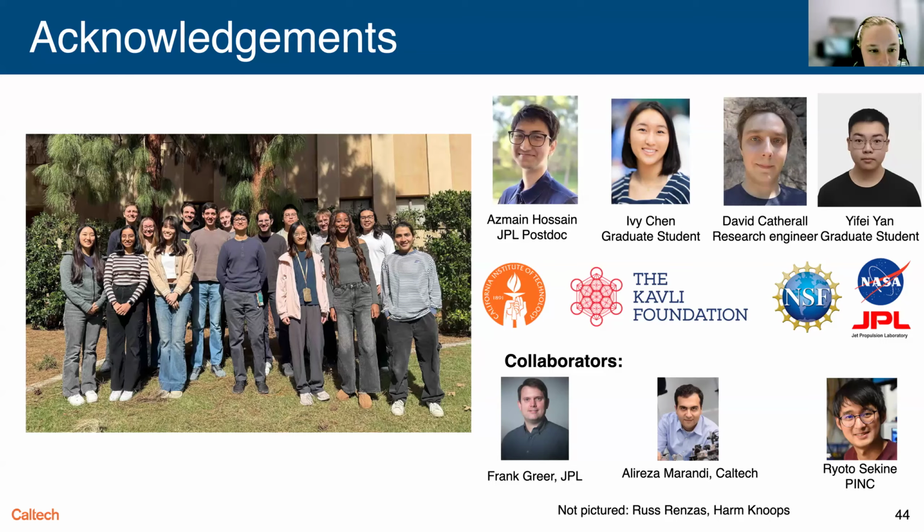And then for your niobium nitride that you were etching, did you deposit that using PVD or ALD? There is a mix of samples. So some were sputtered actually at JPL. Others we have deposited via ALD in that same tool before. That makes sense. You can actually get pretty good niobium nitride by ALD in terms of its TC value. It's actually pretty good.